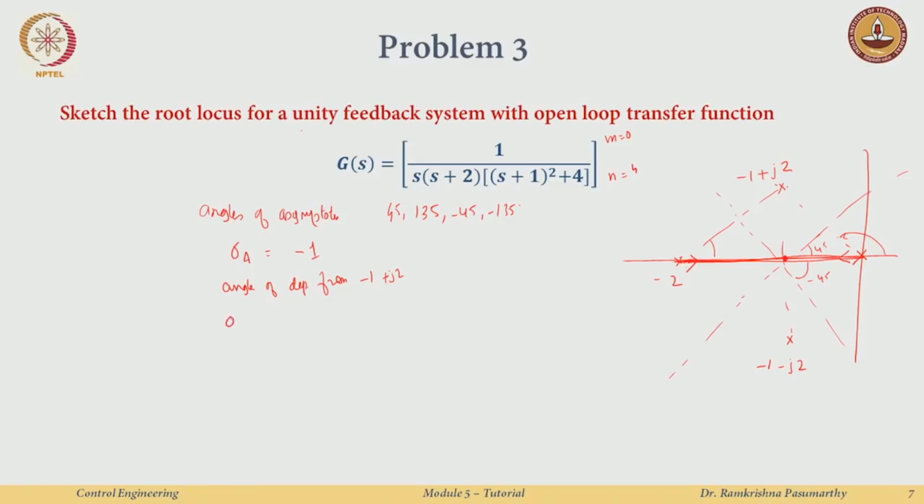So, that phi, angle of departure, is just the negative, if all are poles, it will just be negative: 2 over minus 1 for the first guy, then you will have minus tan inverse 2 over 1, this guy is at 90 degrees, and then I add 180 degrees from the formula and all this will just add up to minus 90. So, this guy will just vanish by itself because you can also see the symmetry here. Okay. So, one thing I know is from here I am moving here, right.